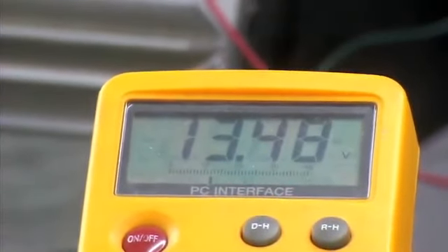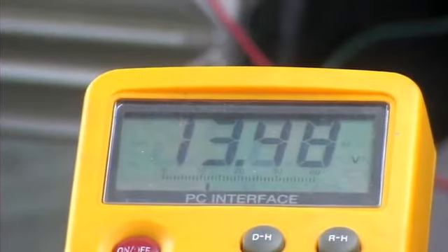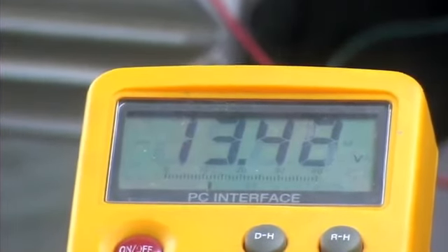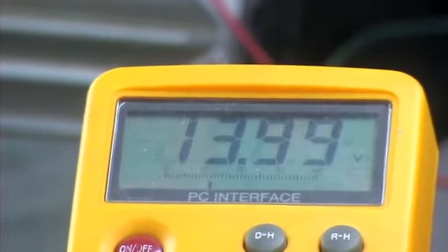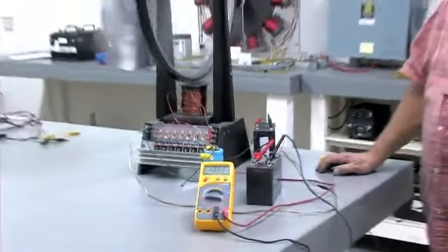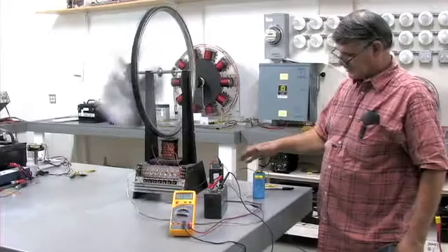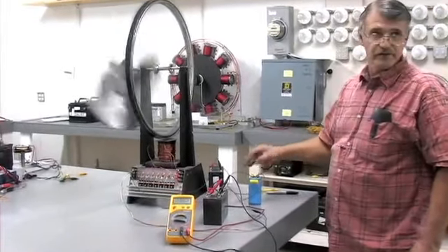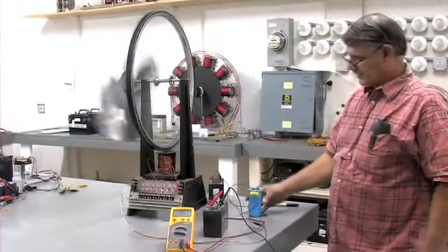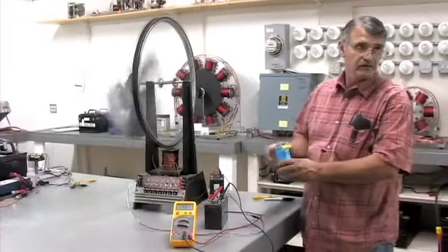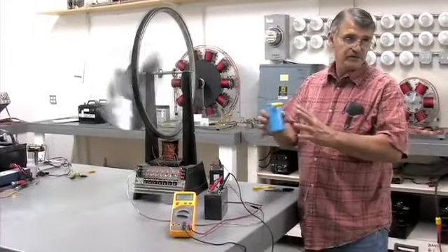You only had that on the capacitor for what, a few seconds? Yeah, less than that. We want to discharge this capacitor. And the other thing is, don't leave the capacitors open, because they sometimes build another charge. Have you noticed that they build their charge when they're near these machines? Oh, no, no. Just after we use them, sometimes they build up another charge, and we think that's the residual left over in the plates as they expand back.